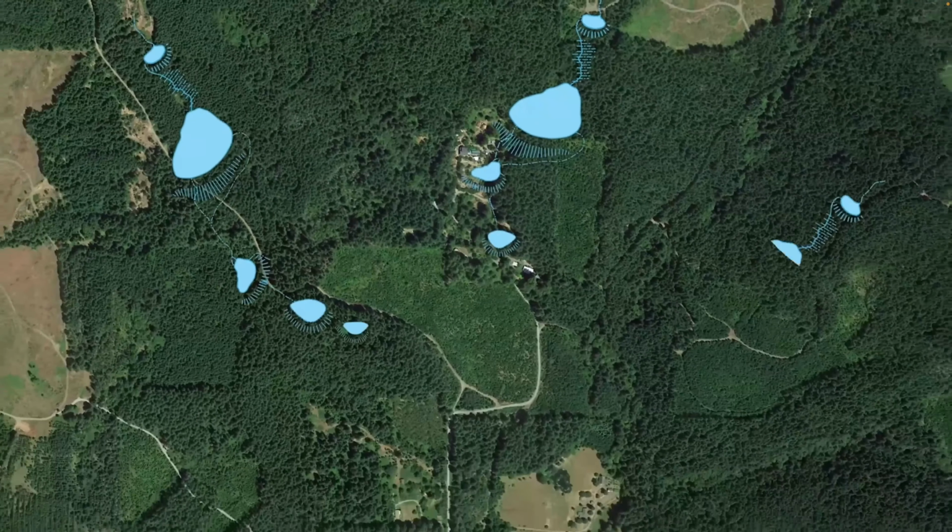Some of the constraints may also lead to further decisions around whether or not, for instance, large stored water is the best choice, or maybe you're going for a lot of just infiltration and bioswales and a different agroecology altogether. Or maybe you do need that stored water, so you're looking to bentonite clays or pond liners or something like that to really adequately hold the water.